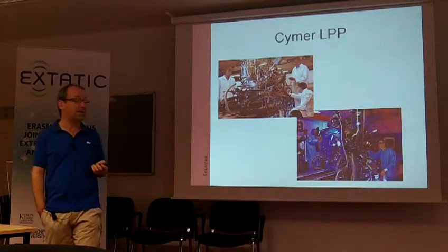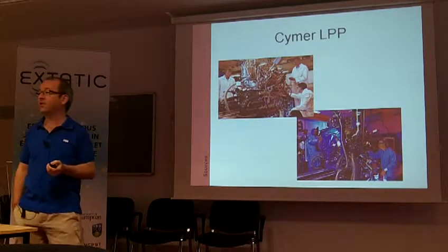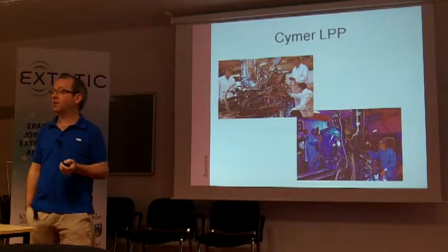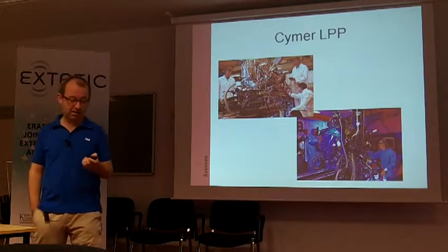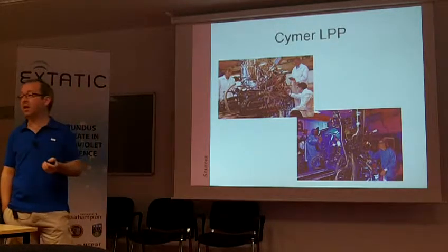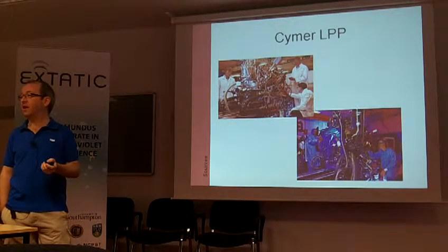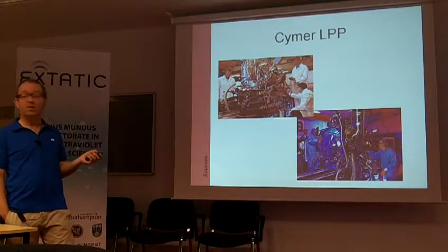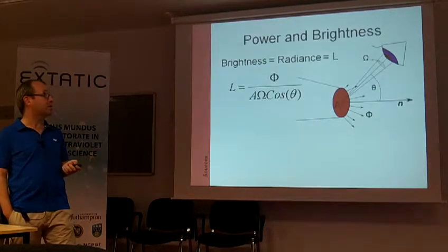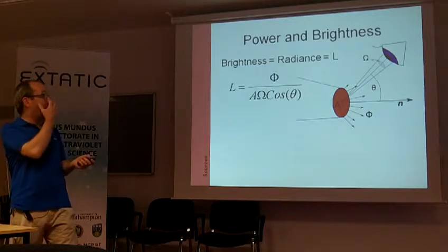The light source currently being used mostly for EUV metrology is an energetic light source which produces about 10 watts of EUV power at 13.5 nanometers, something like that. And that's an electrodeless Z-pinch discharge system as well. So there are no laser plasma systems currently being used in metrology, I don't think.